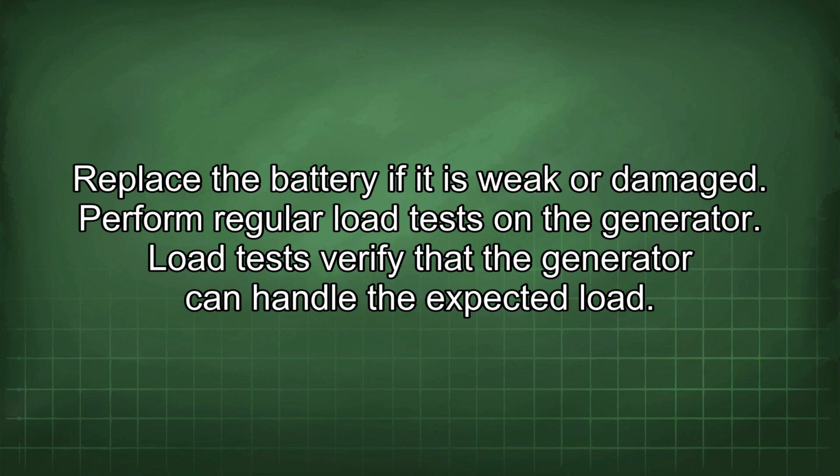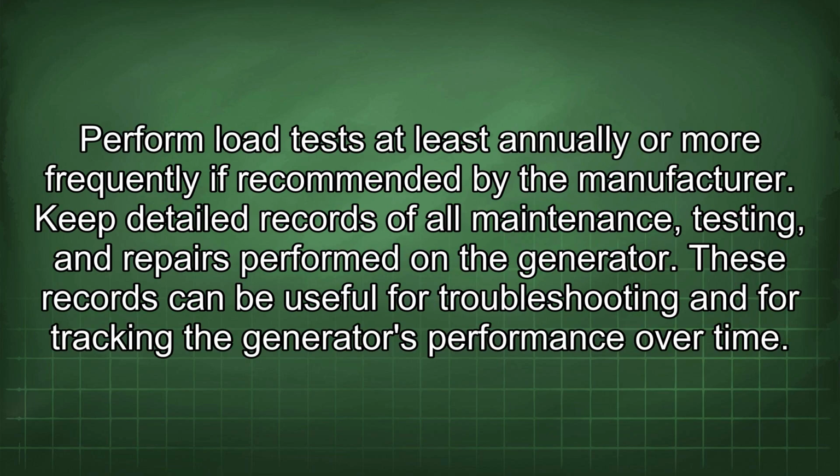Perform regular load tests on the generator. Load tests verify that the generator can handle the expected load. Perform load tests at least annually or more frequently if recommended by the manufacturer. Keep detailed records of all maintenance, testing, and repairs performed on the generator. These records can be useful for troubleshooting and for tracking the generator's performance over time.